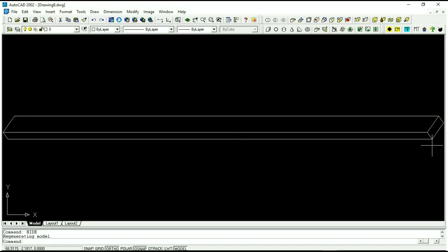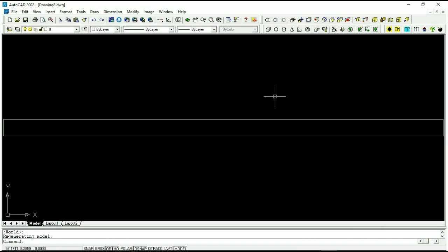You're looking from this direction over here on the right. You can see the end of the stud. Here's the 1.5" side, and here's the 3.5" face. And so when I draw these parts, I draw them in profile. And the profile is with the thickness into the page by my definition. And so when I bring it into my component, when I'm building the components, it's important to know what axis I need to be rotated around when I bring those in.